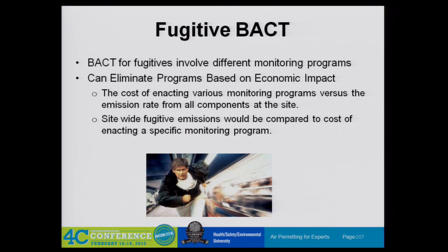They're usually the new flanges and pumps are new units, so they qualify as being modified. And you have to look at what control program is effective. Is it effective to do just a 10,000 ppm leak program or no leak program for the type of emission savings you're going to get by instituting an LDAR program? Well, do you have to go all the way down to a 50 ppm leak program that you do every month to get 99.999% control? Well, there's some documentation now in the literature on what level of control is expected by what level of program, what subpart of the reg generates what level of control is expected.